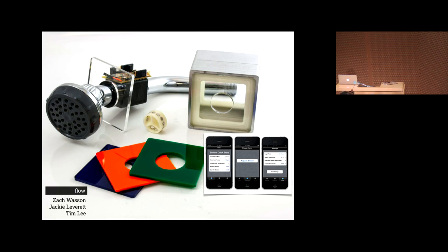You probably don't want to run a power cord into your shower, so how do you build the whole thing so it's self-powered? So here's a 3D printed impeller with magnets on the circumference. Water rushes through, impeller spins, induces a current in a coil outside that's just enough to power up a microcontroller. It takes a reading and sends it over Bluetooth to the phone that has to be somewhere in the room but not in the shower itself.